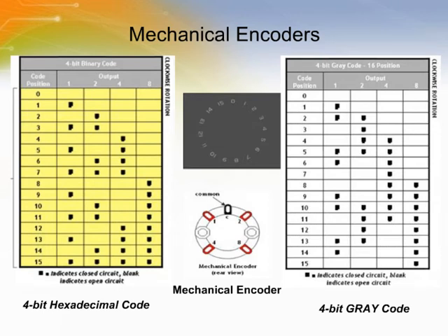This page introduces mechanical encoders. The design and construction of mechanical encoders is similar to rotary switches. Output digital codes can be read by microprocessors. There is a common terminal and 4 additional terminals that could also be referred to as bits. The 4 bits are called the first bit, second bit, fourth bit, and 8th bit.